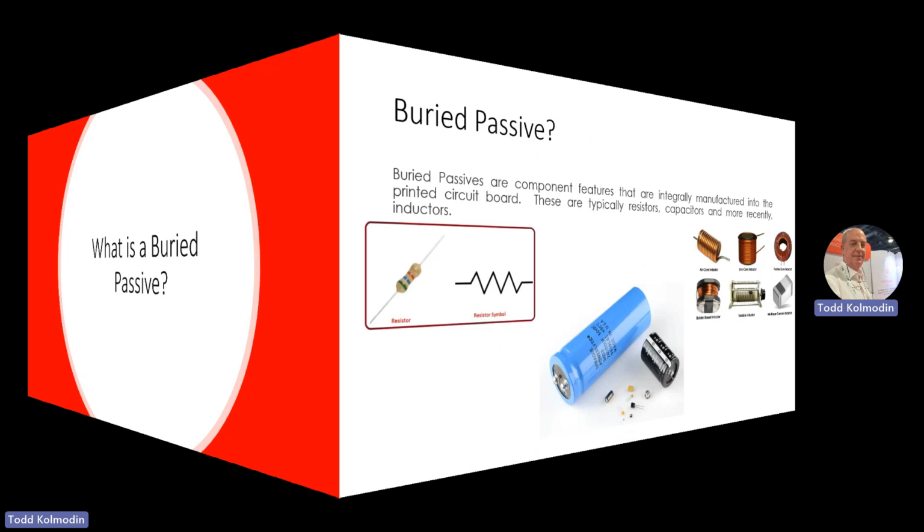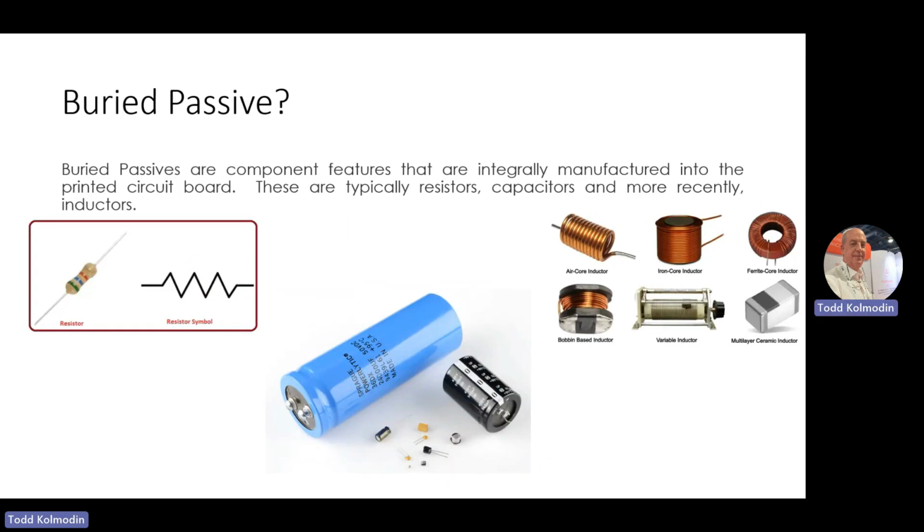Buried passives are a component or a feature that's integrally manufactured into the printed circuit board. These are typically resistors, capacitors, and more recently, we do see some inductor circuits. Resistors, capacitors, inductors all do different functions. They can be by themselves.